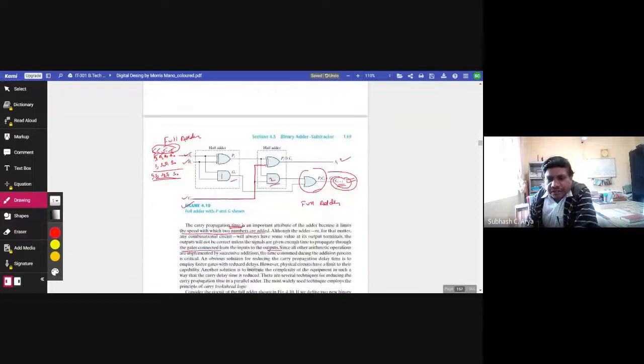So this is the circuit. It starts from the given circuit, that is the full adder, and we give the name Pi to the output of this exclusive OR gate, and Gi to the output of the carry. First and second one, Pi exclusive OR of Ci, which is obviously here.